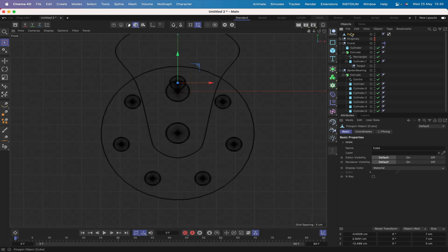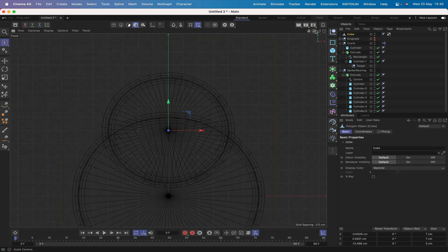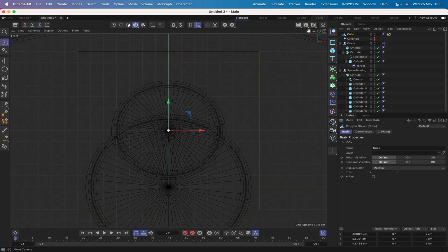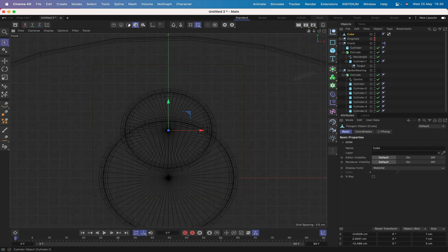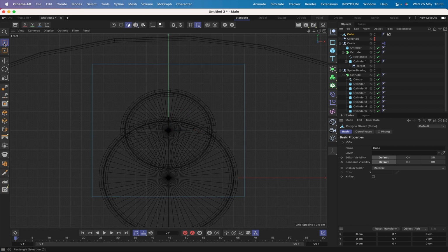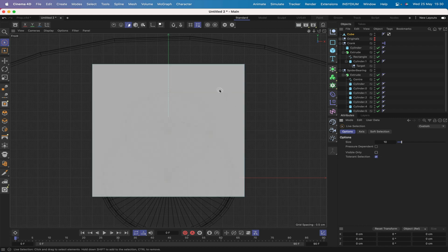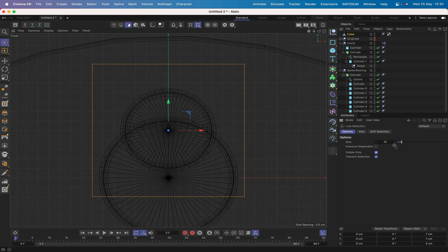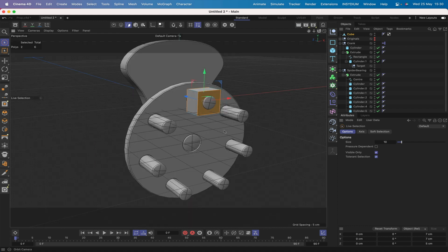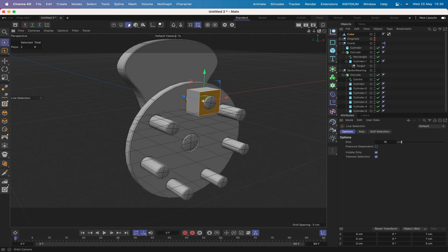Switch to the front view again and hit O for object so that we can see things a little more closely. And then what we'll do is select, in fact what I'll do first is select polygon mode. Just go to live selection. We can click off visible only, click on our front polygon, and that will give us the front and rear faces selected, which is what we want. And then we can hit I for inset and just hit apply to see what we get.